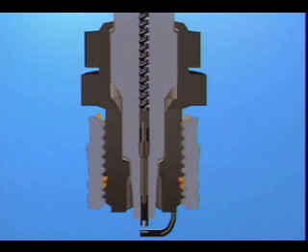If the plug is under-torqued, gases may leak between the threads of the shell and the head. The heat from the exhaust gas can cause the plug to seize in the bore, making it impossible to remove the plug without damaging the cylinder head.